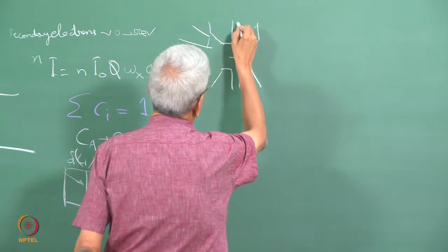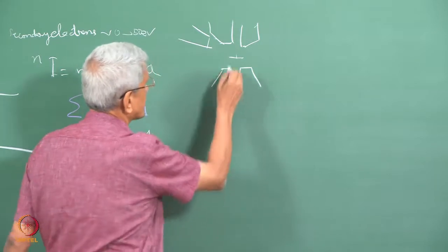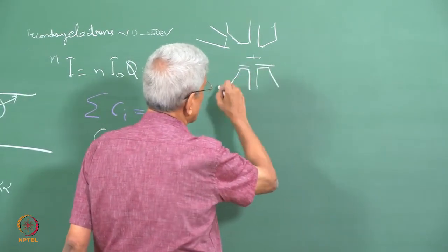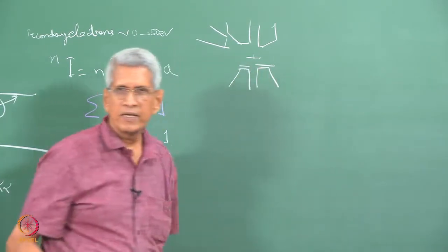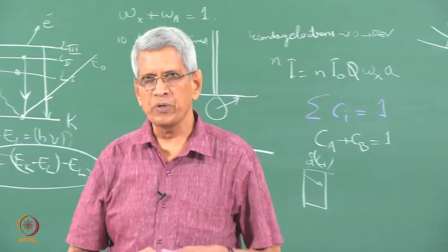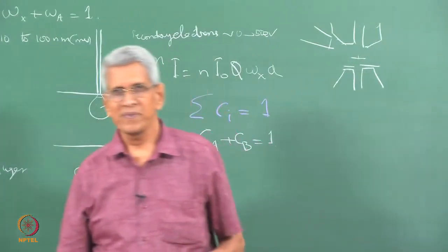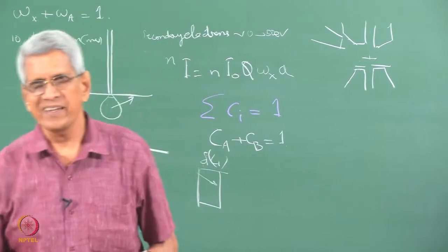The electron beam falls onto the sample and comes out further, but in that process there may be an aperture here or the pole piece, or the copper winding. Everywhere this electron beam can hit and X-rays can be produced. All these X-rays could reach this detector, and they are also characteristic X-rays.